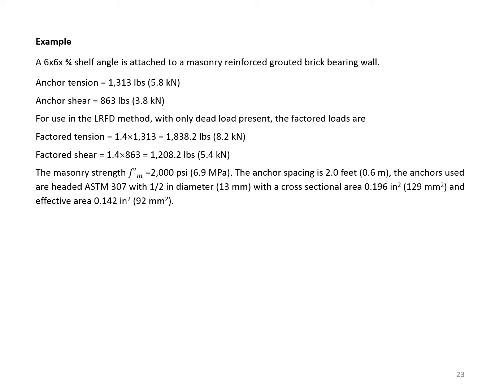In this problem, the anchor spacing is 2 feet. The anchors used are headed ASTM A307 with a diameter equal to 0.5 inches. Therefore, the effective area is 0.142 square inches, as previously given in a table.